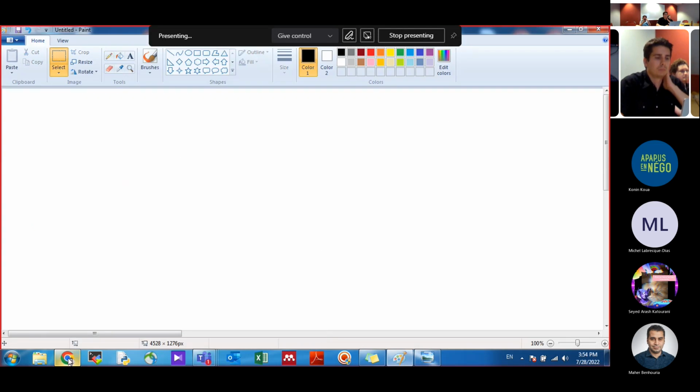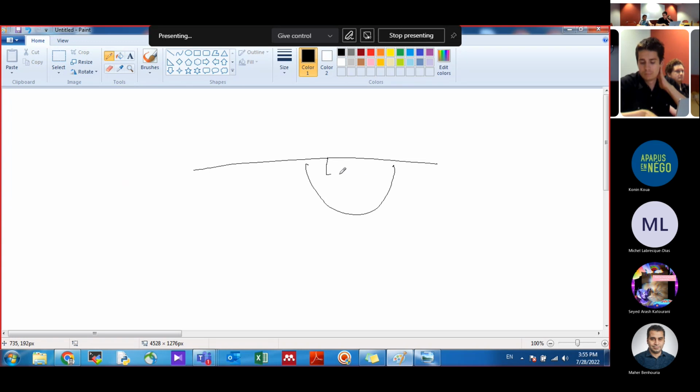So when you have a well to have the PMOSes, these are the PMOSes. They should be away from the border of the well.